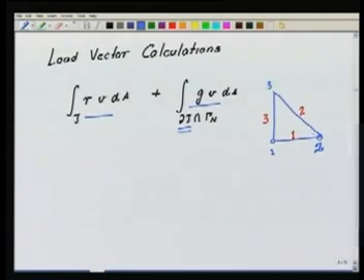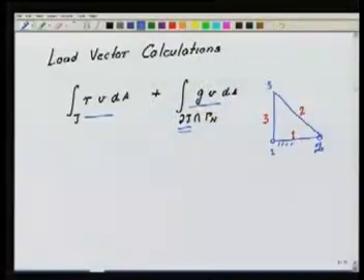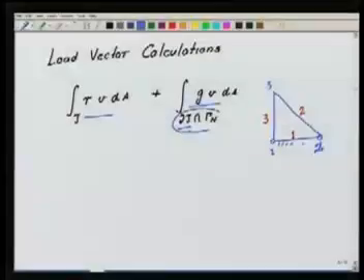So an edge is like a 1D element, and for each edge I have the 2 nodes corresponding to the edge, and I can have either edge 1 or edge 2 or none of the edges lying on the boundary of the domain. And if it is lying on the boundary, I have to figure out whether it is actually on the Neumann boundary. If it is, then I have to apply the Neumann conditions there. So first we are going to talk about this part.